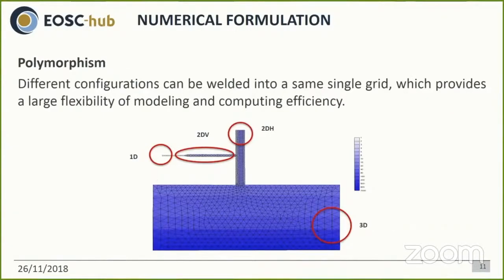The combination of a LSC2 grid and a horizontal mixed element grid provides the user with a high flexibility for various applications. For example, on this figure, the deeper part of the domain is treated with a 3D configuration, but with fewer levels in the shallower parts. Some waters, sufficiently shallow, are discretized with one vertical layer, which is a 2DH configuration. You see also the transition from 2DV to 1D near the upstream river. These discretizations lead to a large computing efficiency and enhance numerical stability.